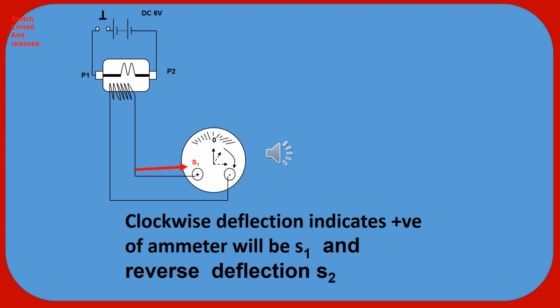But before inspection, I think they are showing it. Okay, but to clear your basics, you should know the system. You connect the primary side P1 and P2: P1 with positive and P2 with negative. A push button switch is there, and the secondary is connected with an ammeter, one terminal with the positive terminal and one terminal with the negative terminal. It is a zero-centered ammeter.